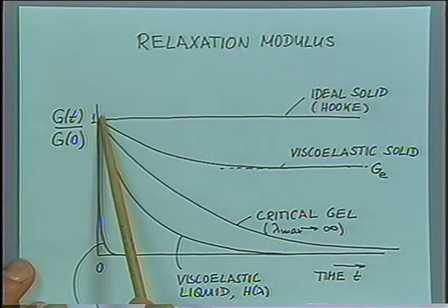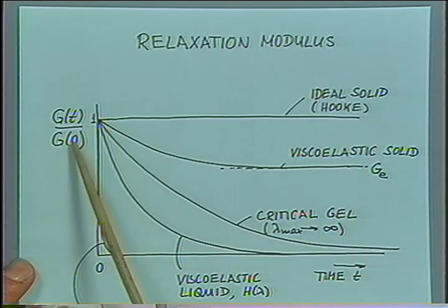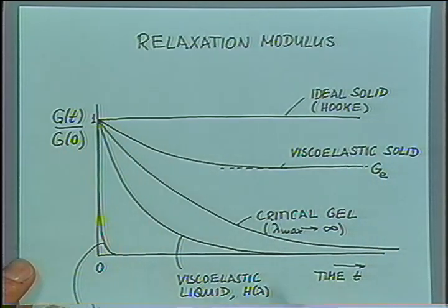Okay, so what is this relaxation modulus? One function defines the shear stress and the first normal stress difference. And this function would be good to know because then we can describe the behavior of polymeric liquids in small deformations. And here I sketched the time dependence of that function for you. It's the relaxation modulus. For the ideal Hookean solid, this would be given just as a constant value. The modulus would maintain its initial value, would not change in time. Time is here our independent variable.